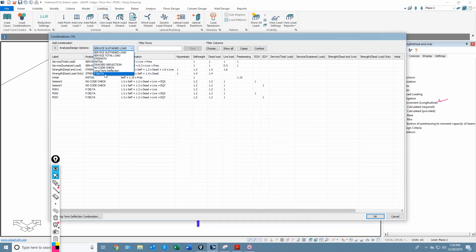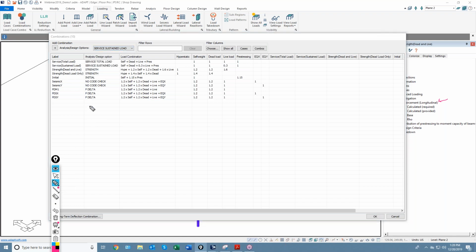So whenever you mark a combination Pdelta, the program is going to check, and it could potentially take longer depending on how big the model is and how you set the combinations up, and I'll describe that. We have two ways to really frame the combinations. We can run singular solutions for each Pdelta combo, I'll call it S, and we can run batch solutions called B.